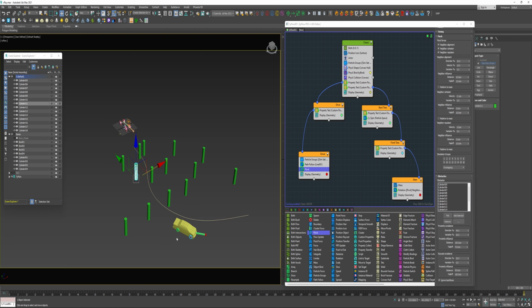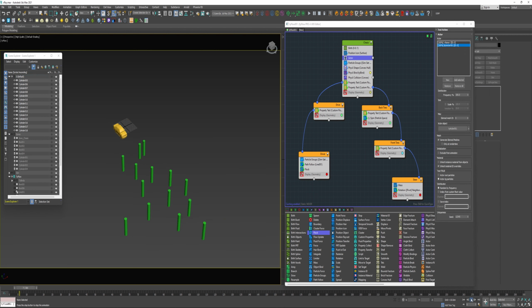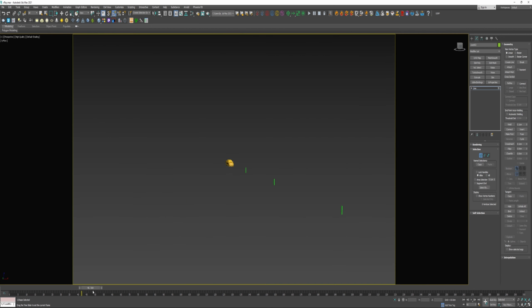if you get any wobble in the wheels, you can increase the time steps and the sub steps in the TyFlow settings. This took a few minutes to set up, but as you can see, there was nothing at all complicated about it. It just further illustrates what a phenomenal plugin TyFlow is and how easy it is to use. In a future video, I will demonstrate how to expand on this setup and add more dynamic elements to the rig to create a more advanced simulation.